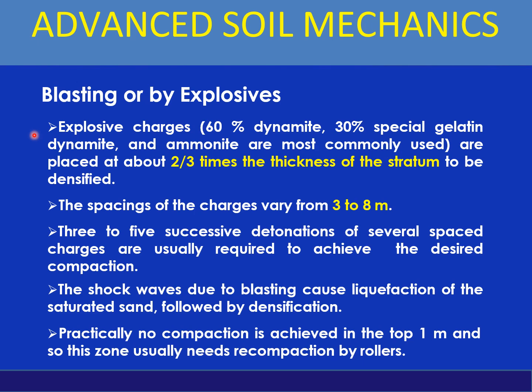Explosive charges of 60% dynamite, 30% special gelatin dynamite and ammonite are most commonly used, and are placed at about 2 by 3 times the thickness of the stratum to be densified. The spacings of the charges vary from 3 to 8 meters. 3 to 5 successive detonations of several spaced charges are usually required to achieve the desired compaction.